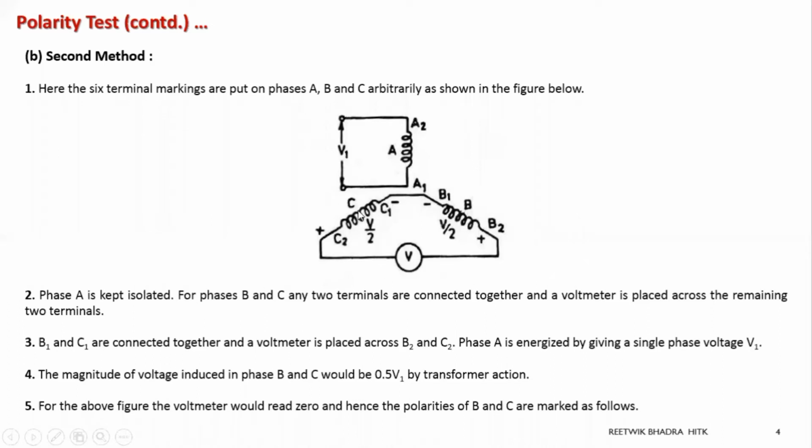Okay. Now take the polarities, whatever plus and minus signs are marked in this diagram, and apply KVL in the clockwise direction. Minus to plus I take plus, then over here if it is plus to minus, I'll take minus, and over here I'm not taking care of this voltage polarity, I'm going in this direction. So minus to plus is additive, and plus to minus gives a decremental value. So plus 0.5, minus 0.5, this cancels out. So this voltmeter should show 0, right?